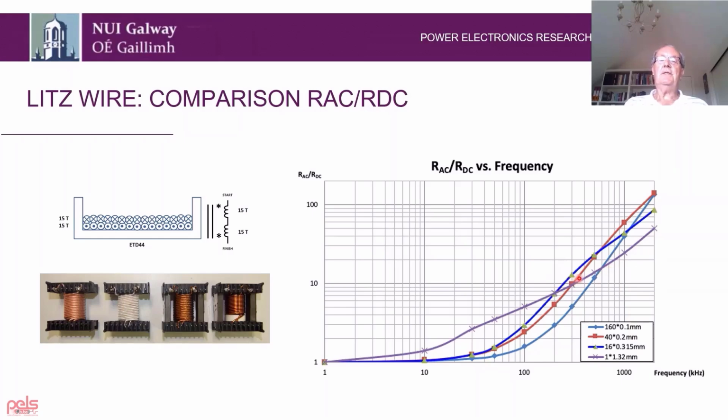So I think this slide is quite useful in that it points out that there's a limitation to how much Litz wire we can use. And in actual fact, if we go to a high enough frequency, it'll become redundant. By the way, we would never operate up here because, as you can see already on this line, our AC resistance is 20 times bigger than our DC resistance.